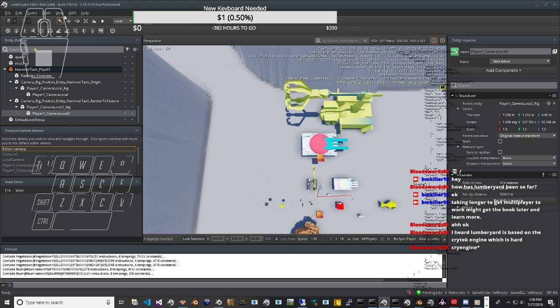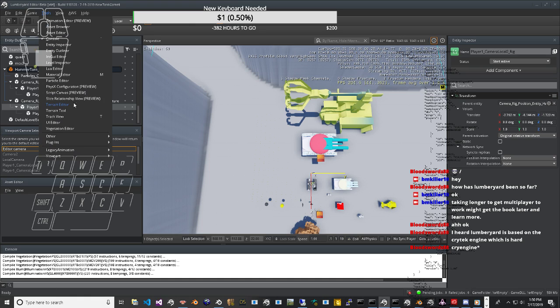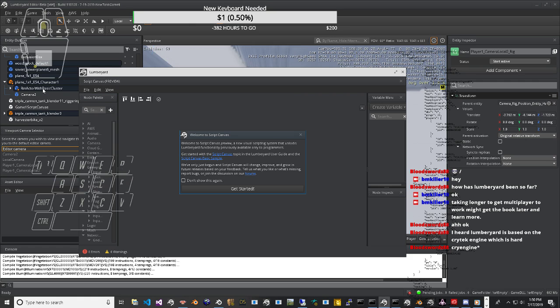The most important input is the slip angle. This is the difference between the actual path line of the car and the angle of the wheel. To be precise, we must define coordinate systems. We'll stay close to the conventions of the Society of Automotive Engineers, SAE, as published by Milliken in Race Car Vehicle Dynamics. Note that this may differ from some frames we've used in the past, but we're going to stick with this set. There's a lot of intense verbiage in the following, but it's necessary to define precisely what we mean by wheel orientation in all generality.